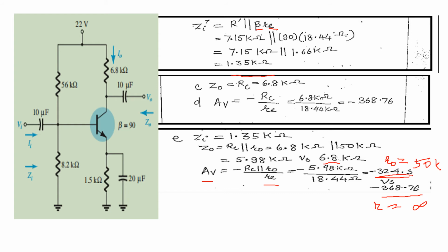when we include some resistive load, the voltage gain reduces. When we apply a load to an amplifier, it can be a speaker in your public address system or a mic. A speaker offers some resistance, which tries to reduce the gain of the system.